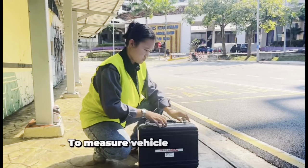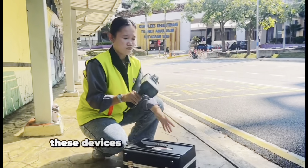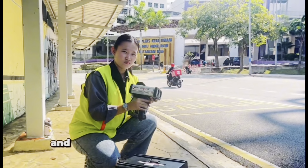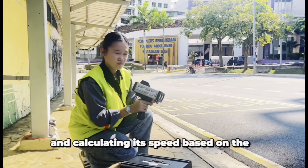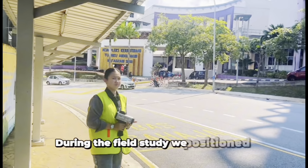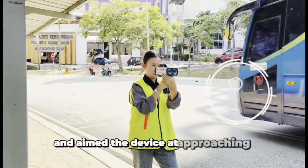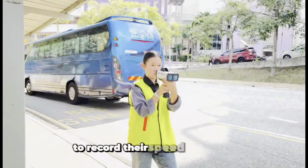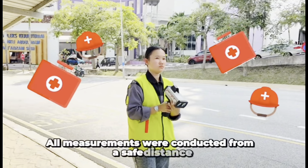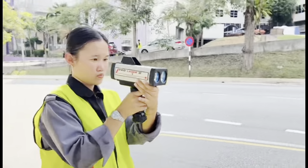To measure vehicle speed more accurately, we use a laser speed gun. This device works by emitting a laser beam towards a moving vehicle and calculating its speed based on the change in distance over time. During the field study, we position ourselves at a safe location and aim the device at approaching vehicles to record their speed readings. All measurements were conducted from a safe distance to ensure the safety of the team during data collection.